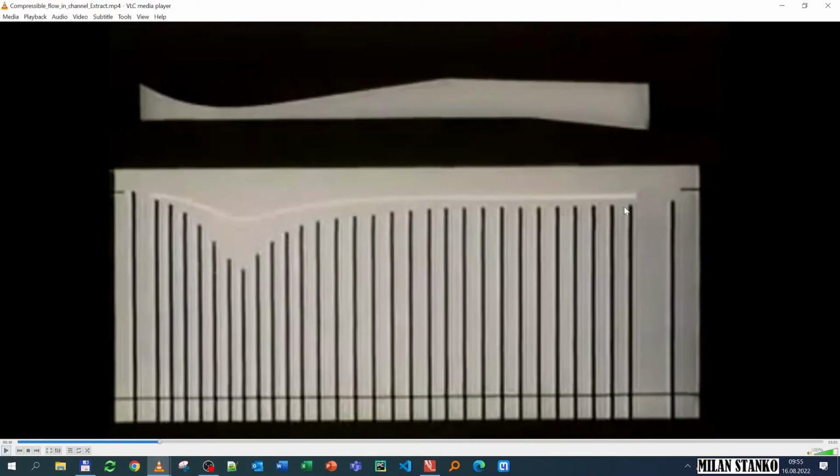And you see what happens is that this is the pressure that is being reduced, and you see that the pressure at the throat actually goes down. So that means that the velocity is increasing. So here the mass flow is getting higher and higher and higher.